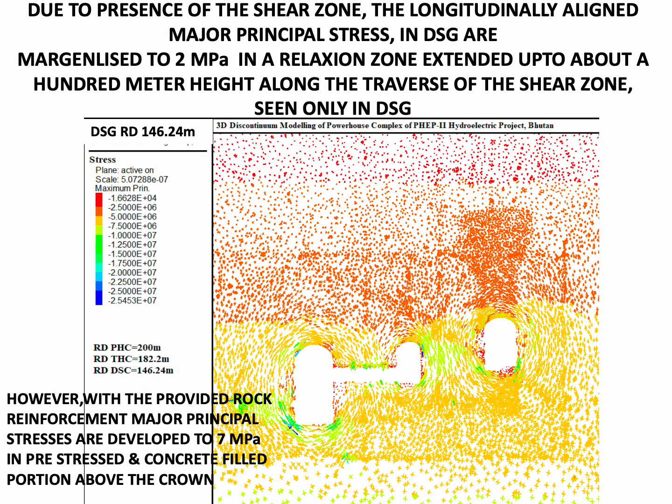The results of the 3D numerical analysis carried out in 2018 by NIRM show that the value of major principal stresses, which are aligned parallel to the longitudinal axis of downstream surge gallery in this reach of hanging wall, were reduced to a value of 2 MPa after excavation had reached a depth of 35 to 40 meter in downstream surge gallery, as compared to the in situ major principal stresses of 4.02 MPa that were present in this reach before excavation.